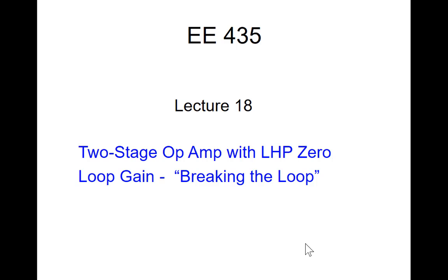What does phase margin tell us about a feedback amplifier? Tell the same thing. If it's second order low pass, it tells the same thing. If it's not second order low pass, you can do a partial fraction expansion. You can still get overshoot and ringing, right? So pole Q still gives us overshoot and ringing information in the magnitude response. Phase margin? Not a whole bunch.